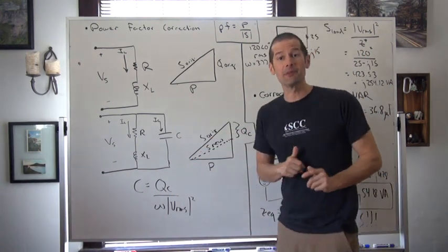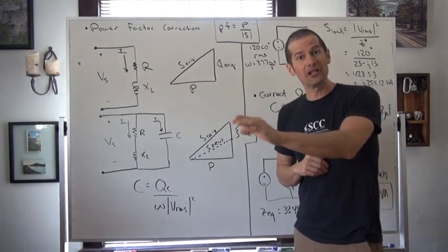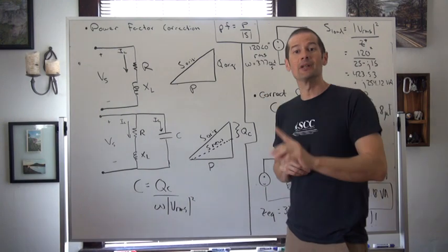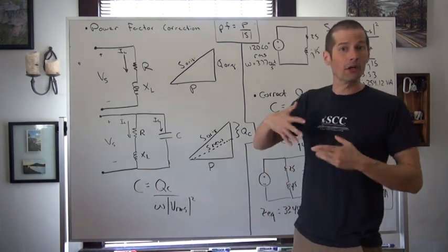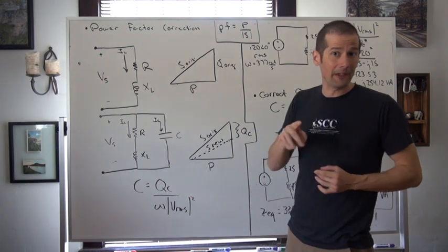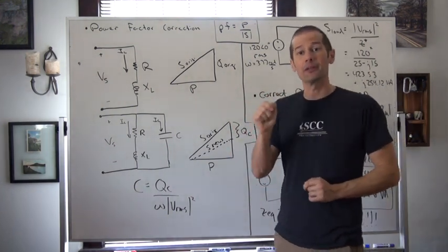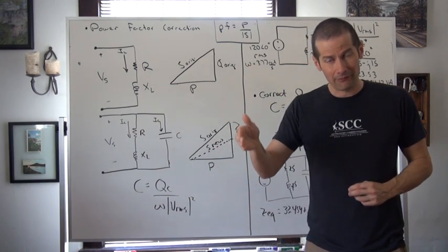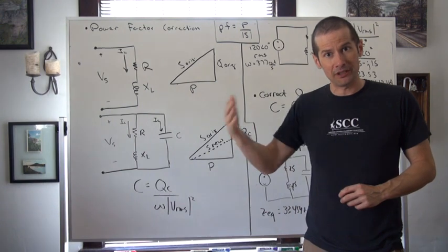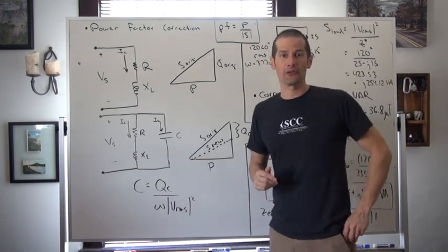And as we have said before, for resistors, the phase angle of the voltage and the current is exactly the same. So if the power we're delivering has more of an efficiency or power factor, to where theta V minus theta I gets closer and closer to 0 degrees, then we're mostly utilizing power that we're actually going to be absorbing and burning up within the resistive portions of the circuit.